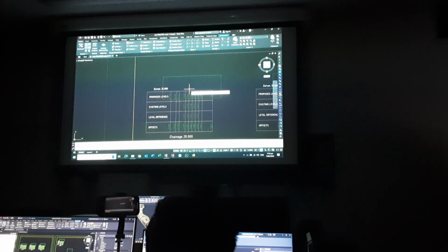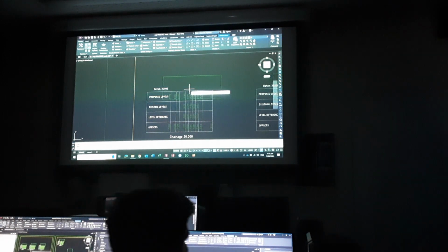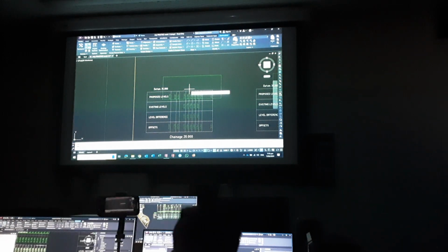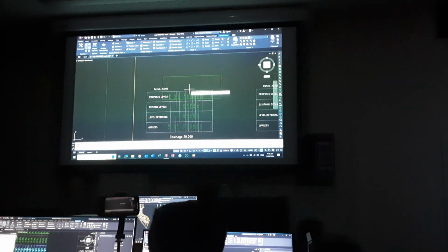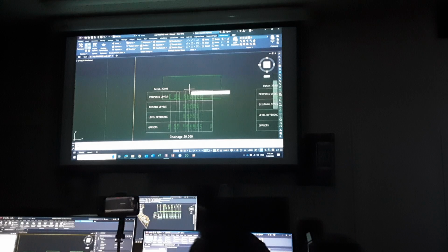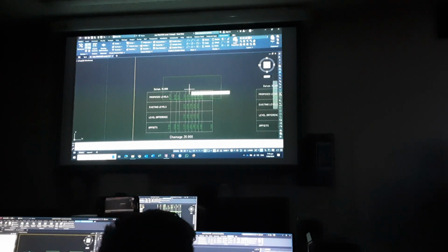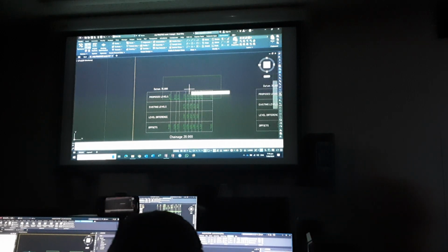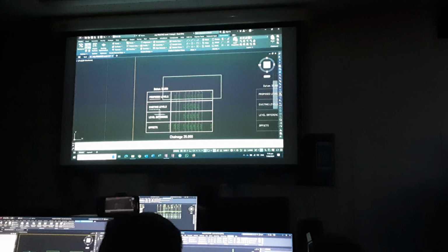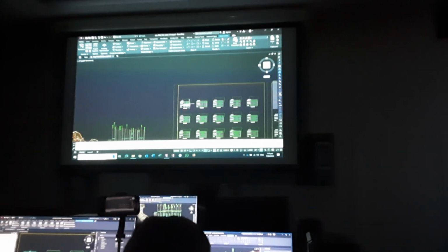If you put the data bands with EG on section 2, it would have done it the right way around. So it's all part of the learning process. We did that slightly wrong, but at least you're going to get the numbers. So either repeat the process with the data bands around the right way, or edit the numbers in AutoCAD. Section 1, section 2, EG.